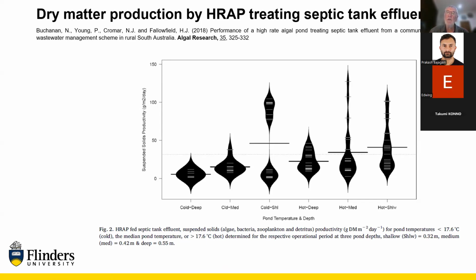They are not pure cultures of algae. They have algae, they have bacteria, they will have some protozoa because the algae and the bacteria are food for other organisms, and they'll occur in your wastewater and they'll come in on duck's feet just as much as anything else. So you have algae, bacteria, protozoa, zooplankton.